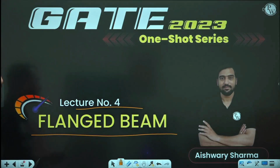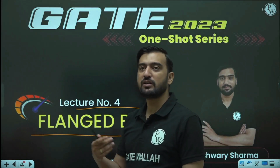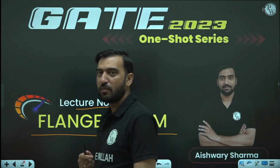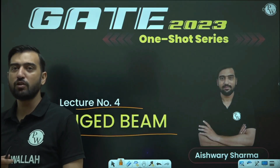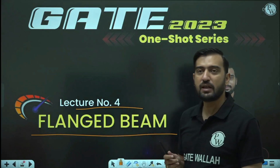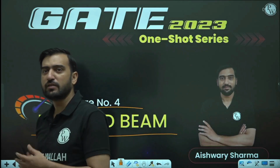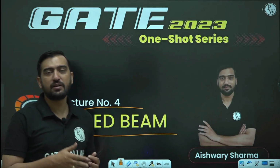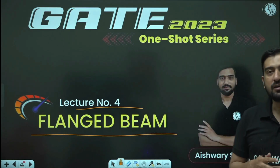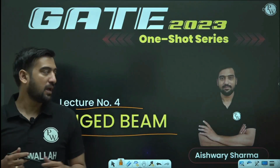Basically the flanged beams are those which have flanges, like I section, T section, L section. But in RCC structures, most of the flanged sections which we are going to use are T section as well as L section. Generally L sections are used at the end of the slab, and intermediate beams between the slabs are considered as T section. I will try to show you diagrammatically.